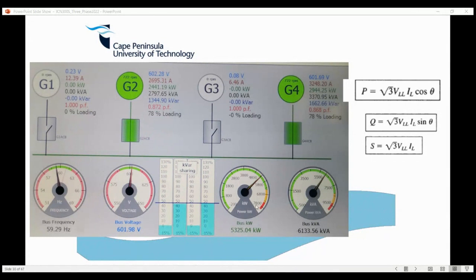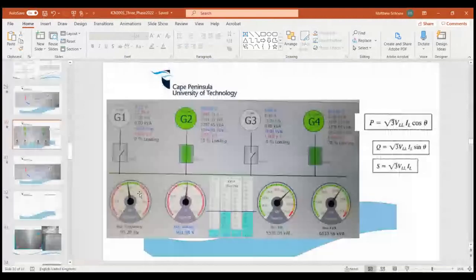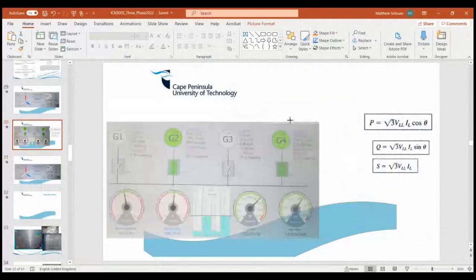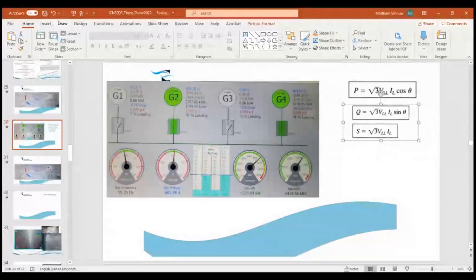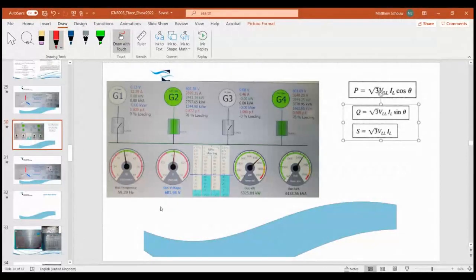How do you do the sine theta when they give you the power factor? I thought the power factor given there is cos theta. Yes, so I'll do it now. Don't worry, just get yourself down and play around. This is just a warm up so you get comfortable with this. As Mr. Ball said, we want to find the angle first. There are many ways to do it. Your power factor is equal to cos theta, so we can go cos second function 0.872, and we can get what theta is. Let me write it at the bottom there.